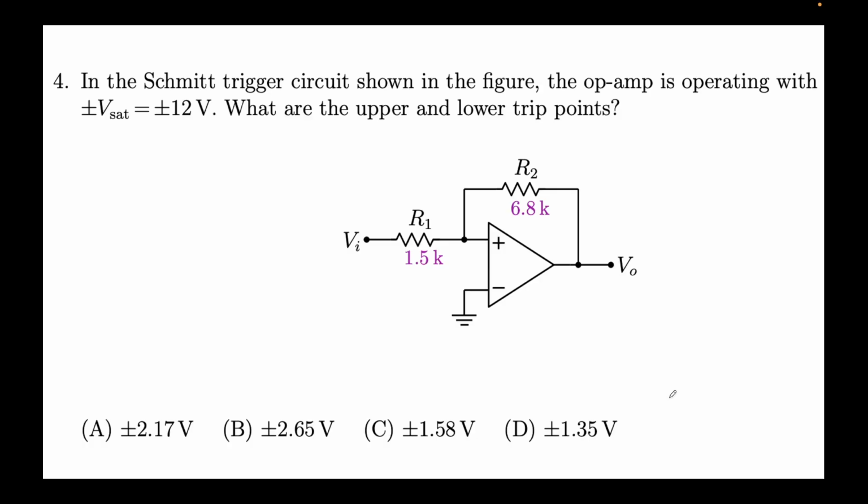If you have any comments or questions, feel free to ask, because now we are going to switch to a different problem. But the concept remains very simple. You just need to make sure what happens at very low voltages firstly, secondly what happens at very high voltages, and when does the switching happen. So these are the only three things you have to keep in mind. And since Rin is very high, we'll assume no current is flowing. So it's just very simple, just KCL at just one single node and nothing else. Okay, so now moving on to the next question.